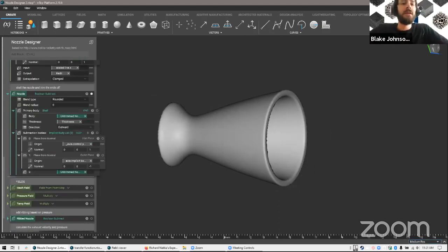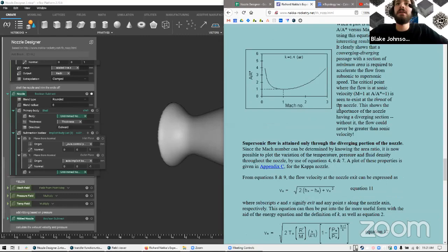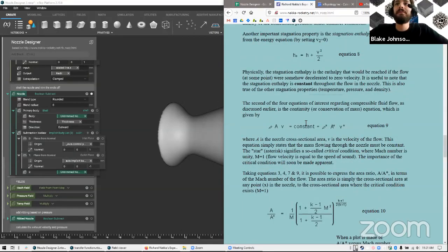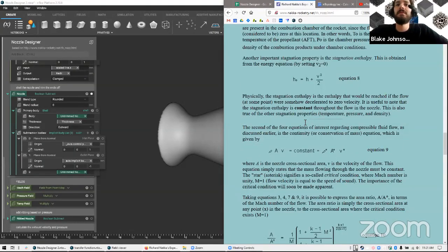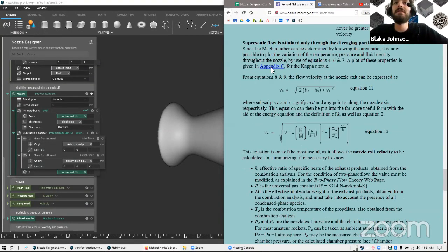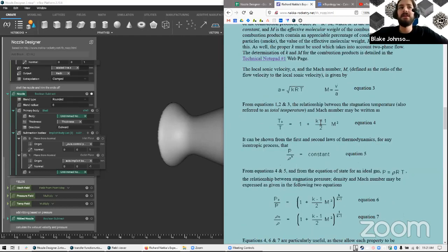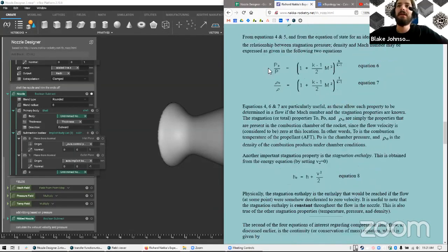And another cool thing, if we go back to this page, we learn more things about the relationship between the thermodynamics and the geometry. We can go up here and we can learn that, well, if I have the Mach number and I have this specific heat ratio, which is just a constant, I can actually figure out the temperature distribution and the pressure distribution of the gas that's flowing through the nozzle.